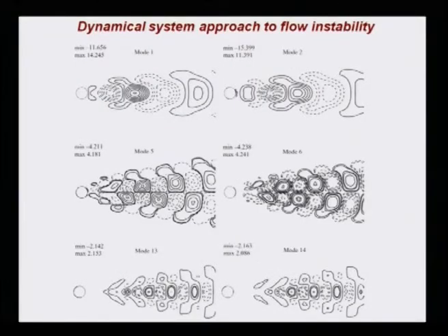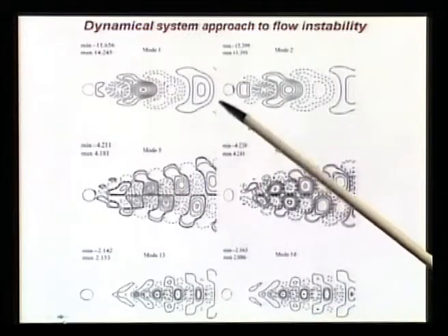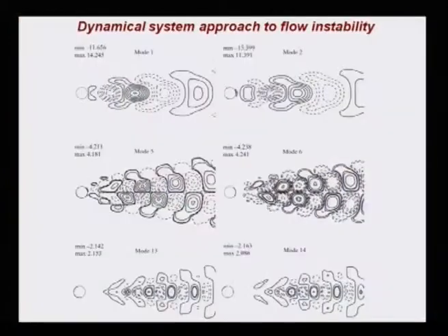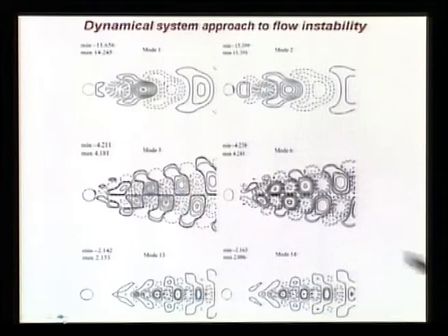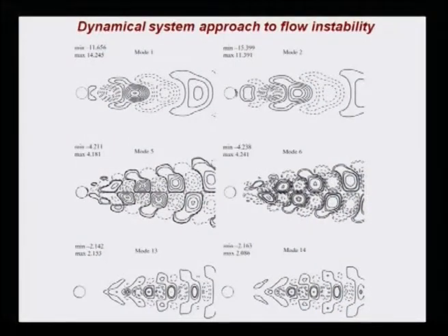This is your case B, where we have just looked at the data set from 350 to 430. And you can very clearly see 3 pairs. That is it. And that takes care of everything. So, if you are trying to exploit POD analysis in terms of flow control, etc., and if you are only interested in the steady state, then probably taking a small such data set once you have reached the equilibrium stage is quite good.